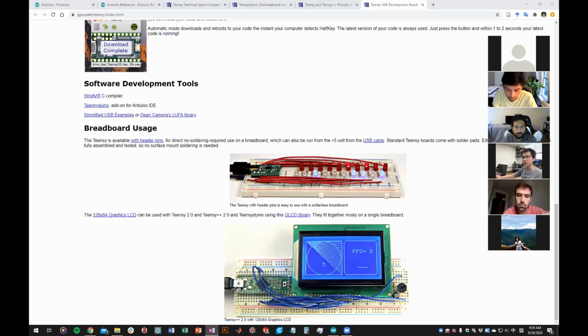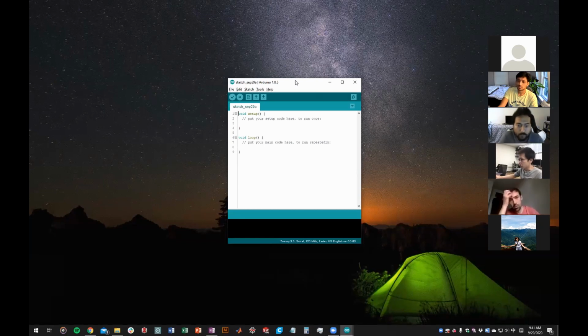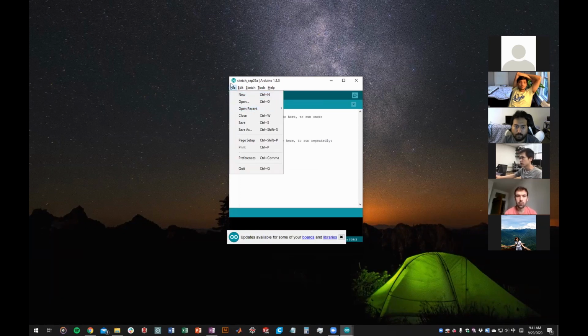All right. So we finished the first part, and now let's move on to the second part, from hello world to task protocols. This is an empty Arduino sketch. First, does everybody know the difference between setup and loop? The code in Arduino runs mostly serially. The code in setup will be run once, and the code in loop will be run an infinite number of times, going top to bottom, top to bottom. So let's first look at an example.